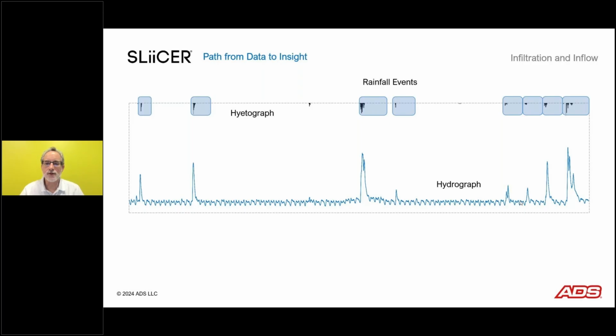In fact, that's the way most of us probably look at rainfall data, in some type of daily total format. And when it comes to I&I evaluations, the daily totals may not be exactly what we need. What we need to know is when it started raining, and we need to start the clock, or start the counter, if you will, at 0 when that event started, and get a total on the rain event.